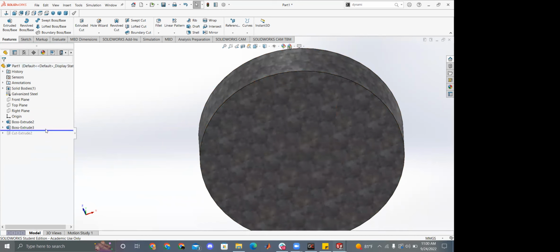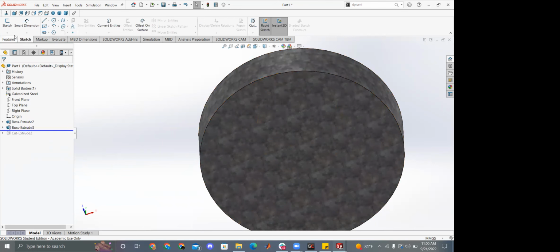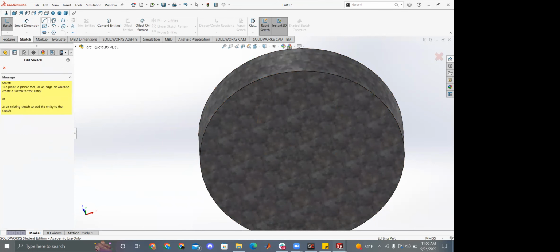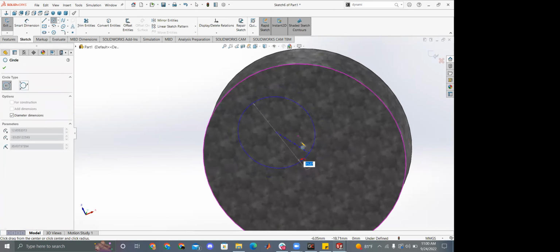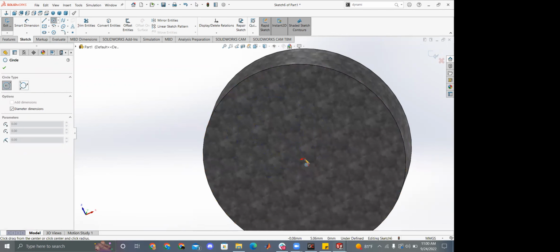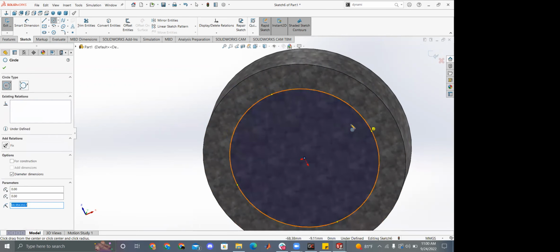If you're going to be putting a feature in a place that a lot of things will depend on, it's good to use the rollback bar, because that will make sure that if you have to delete anything that's not rolled back, you won't affect the other thing that you're putting in this space where the bar is. Like say I wanted to put another circle here.